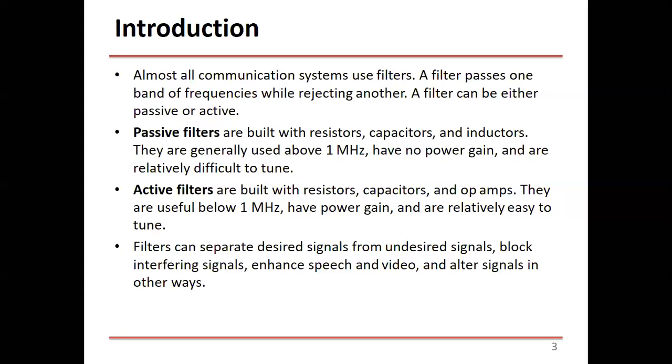So what's the difference between passive and active? Passive has no power gain, okay? They don't provide any power. They are not connected to the VCC or VDD or VEE and so on. So by having this kind of passive filters, it's difficult to tune. If you'd like to change the frequency to tune it from one center frequency to another, this is not easy.